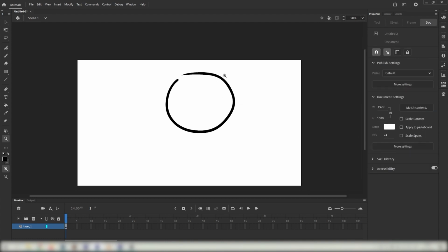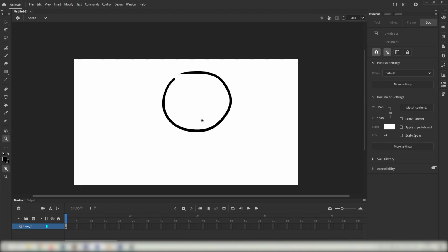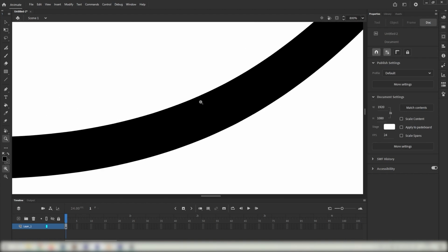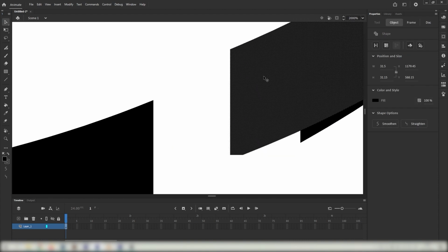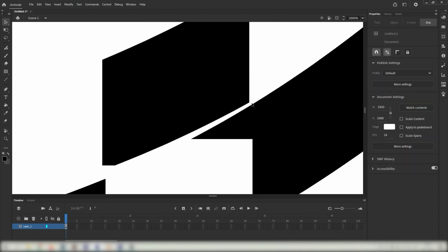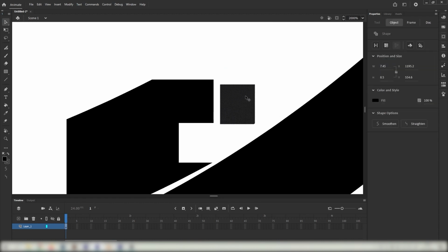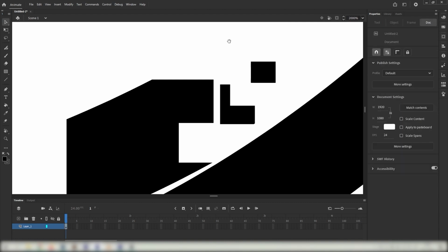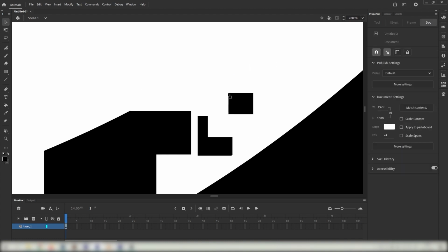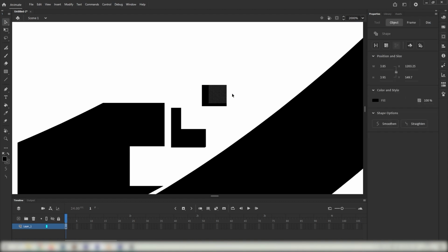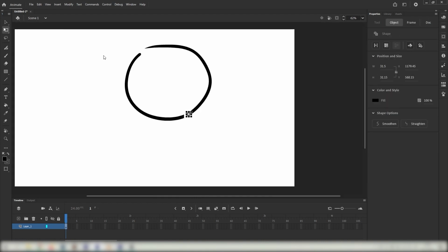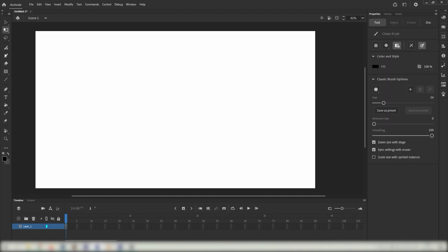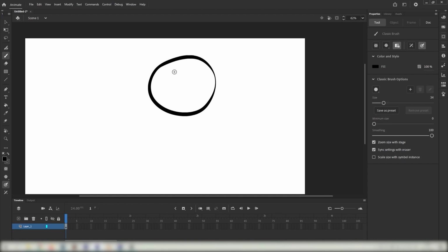It means that when we draw, it's vectorized, which is code for it doesn't matter how far we zoom in or how much we screw around with a drawing, we are always going to maintain a level of quality, versus in Photoshop where it's rasterized, which means the canvas is pixelated, so if you distorted something, you'd be able to see degradation of the pixels. Interesting feature. Zoom in again. So yeah, the brush tool works similarly to Photoshop, but vectorized.